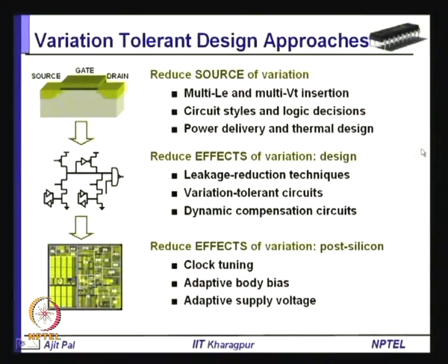So, you have to use a sophisticated power tree, by which the supply voltage is distributed within the chip, and also the thermal design has to be done. You have to do placement of the devices in such a way that there is no hot spot in a particular chip area. That means the heat is distributed uniformly throughout the circuit.